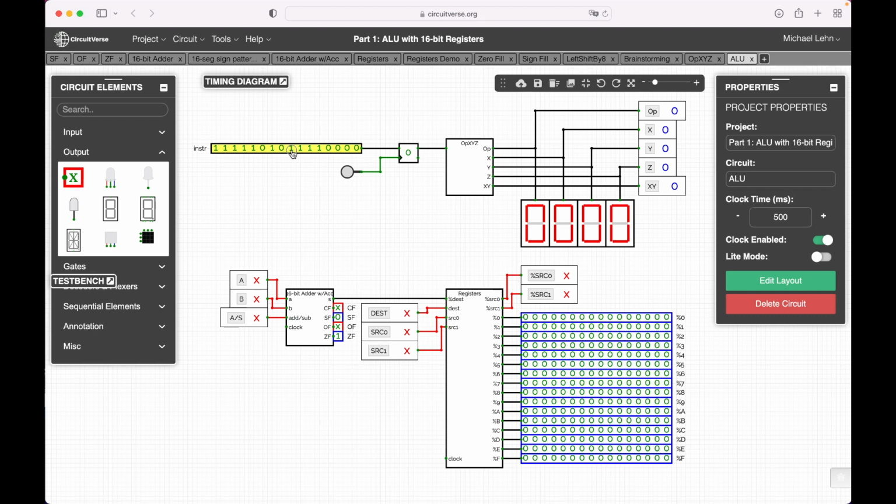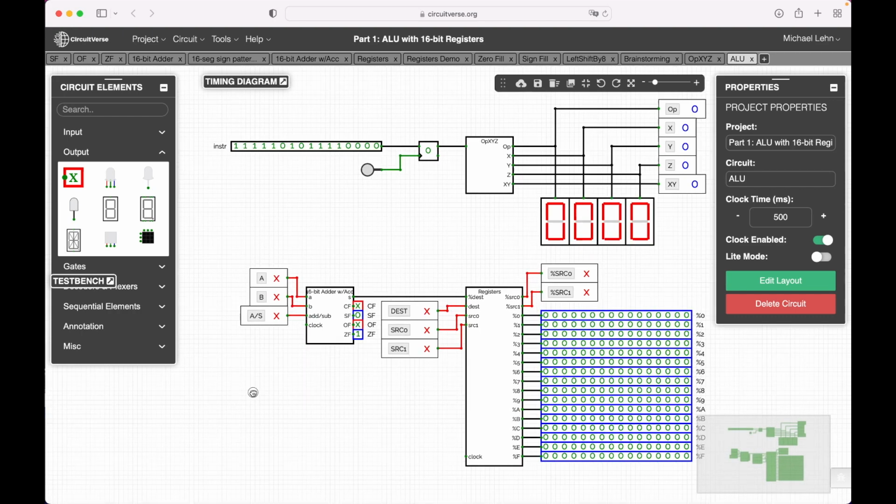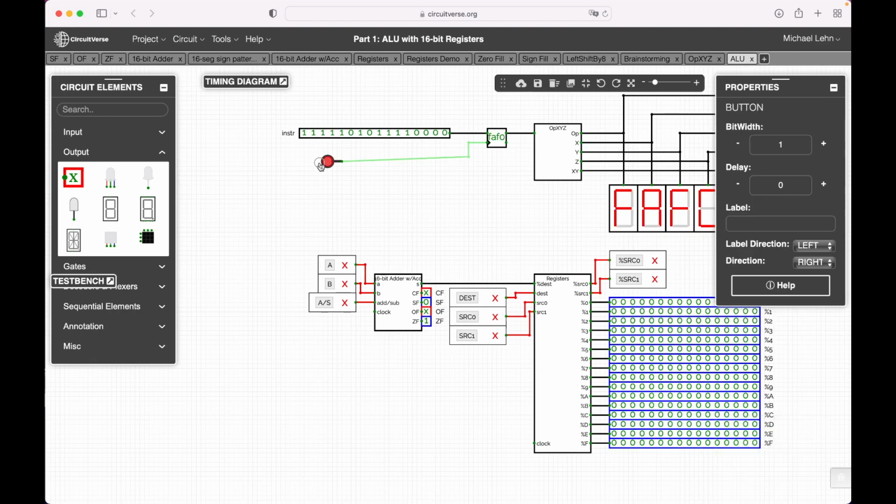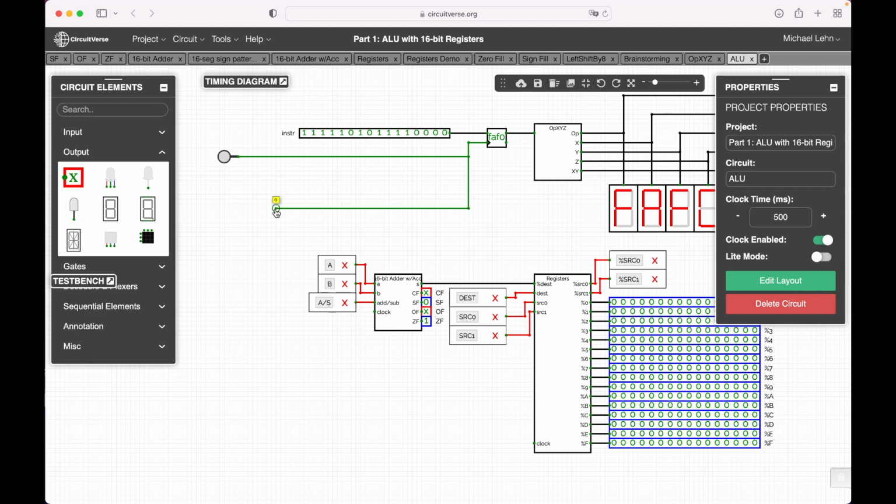Now we actually can do one last thing in the preparation. We have for this register a clock signal. We have a clock signal required by the adder and by the register bank. And actually we can use one clock input signal for that. Whenever something was loaded into the instruction register, we know that it's anyway for the ALU. That means in this case, somehow directly these operands are determined and we directly can compute the result and store it in the accumulator. So we can directly take this clock signal.